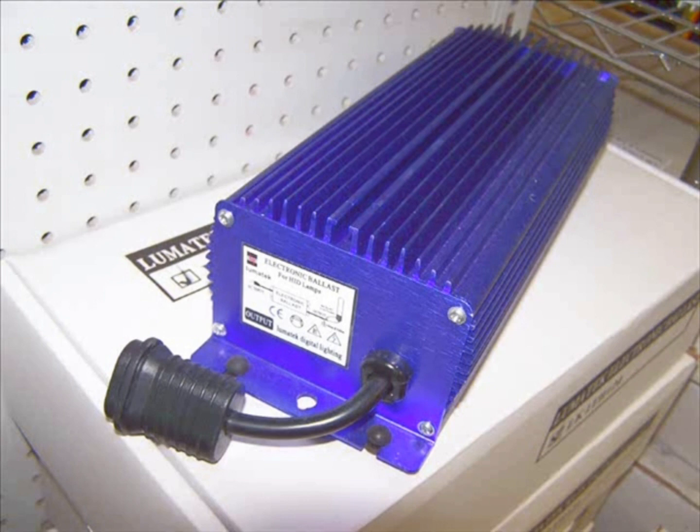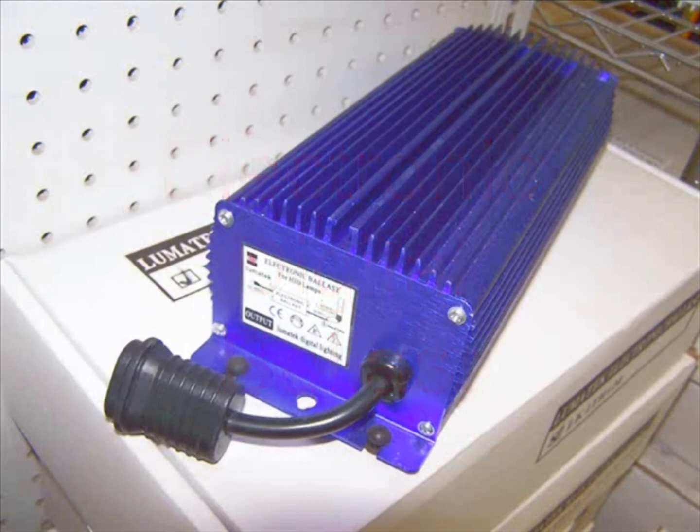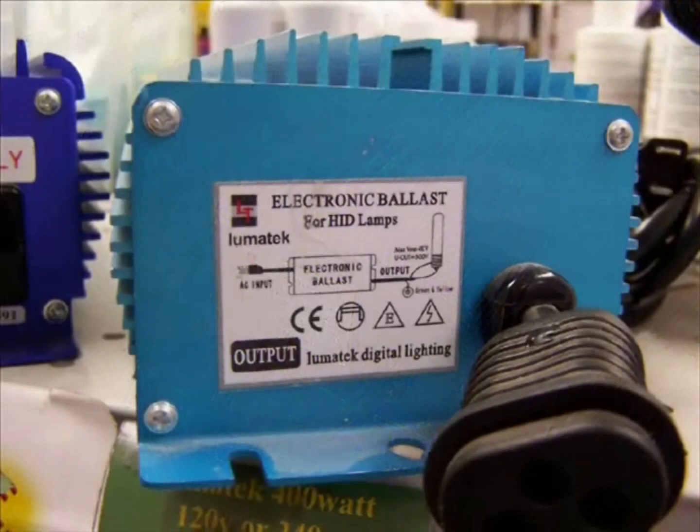A newer, more modern ballast option is the electronic digital ballast. The advantages of the digital ballast include: number one, it is much lighter, which of course makes it easier to install, and perhaps a more important advantage is that a single ballast can activate either a metal halide or a high-pressure sodium bulb.